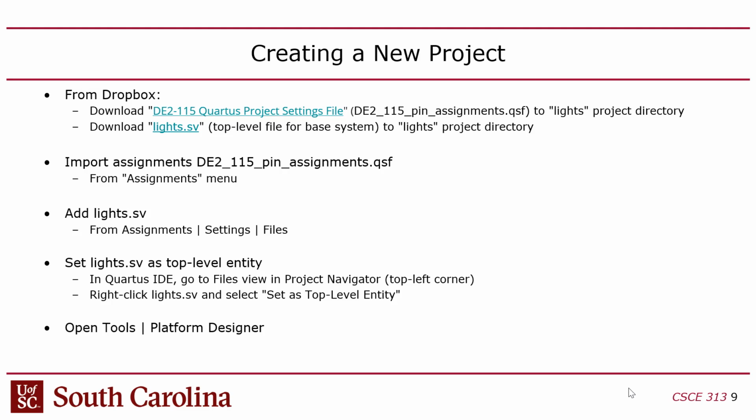The FPGA is on a BGA, a ball grid array, and I think the rows are numbers and the columns are letters, so it's like an Excel spreadsheet. The pin mapping file maps each of those, like pin C17, for instance, to a name, which might be RGB red 6, right? So in order to use symbolic top-level I/O pins that correspond to pins on the FPGA and thus devices on the board, you need that pin mappings file, okay?